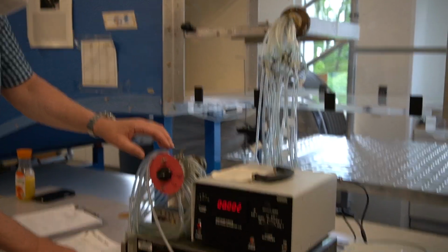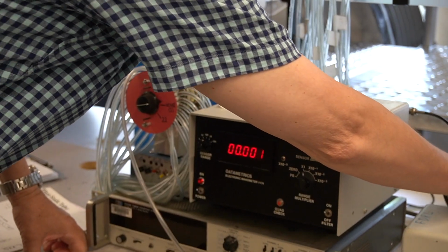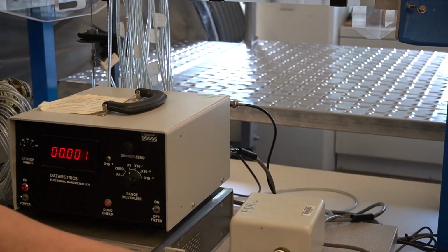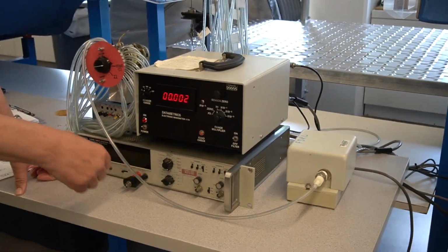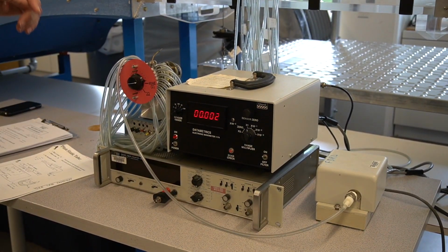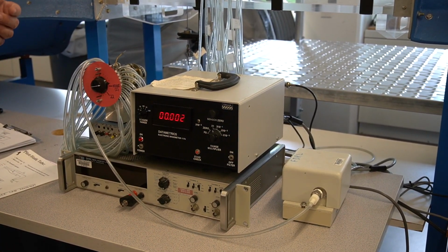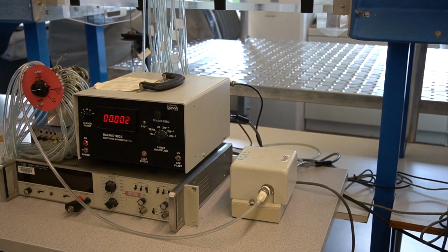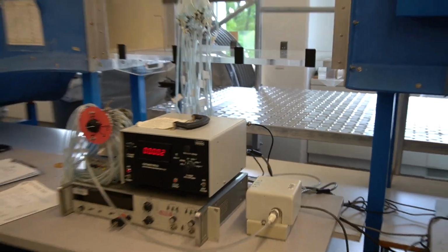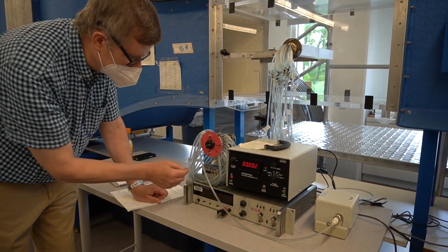What you do in this machine here is you measure, actually I'll show you, static pressure down here is this tube here. Measuring total pressure with this tube here. So what you're going to try and do is everywhere we measure pressure, you're going to measure it relative to the static pressure. So you're getting P minus PS, and from Bernoulli's it's half rho U squared. And then on the other side, you're going to start off by measuring PT, comparing it to PS. Then, as we turn this thing around, we're going to sample different holes one at a time.